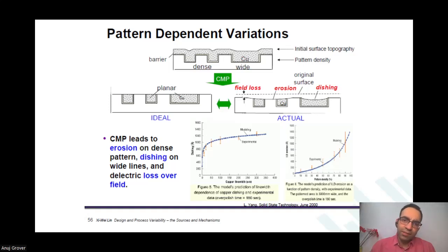Now, do you realize that R and C values are moving differently, is it not? Yes, sir. R reduced by 20%, C increased by 10%. RC would move in a different direction. Anyway, the two wires, word line and pre-charge line, are not matched if they do not have similar density of wires around them. Yes, sir. Absolutely. That is the point that needs to be established.